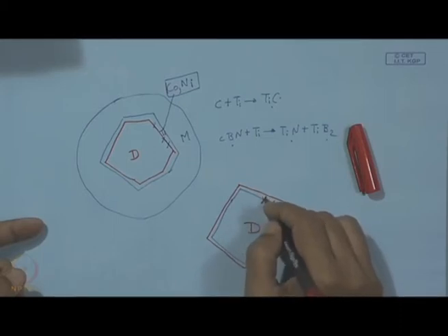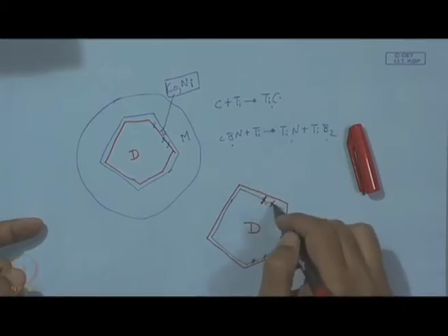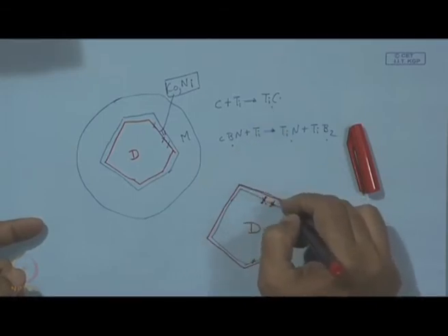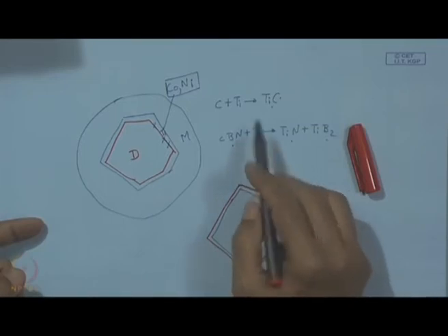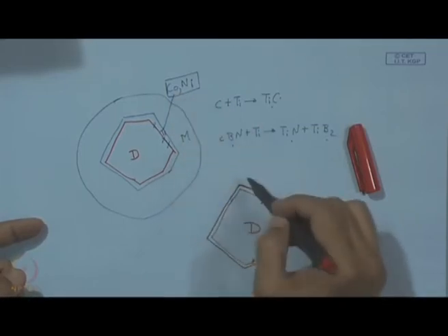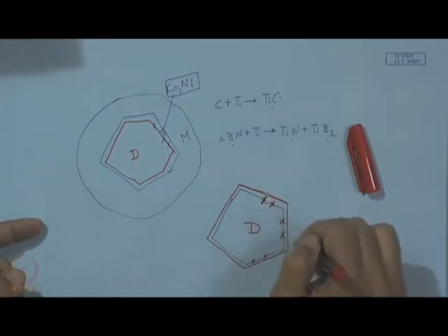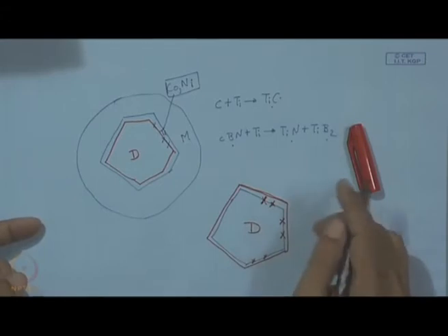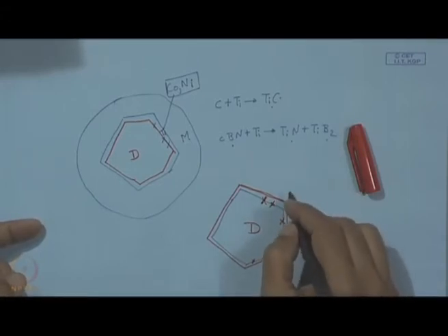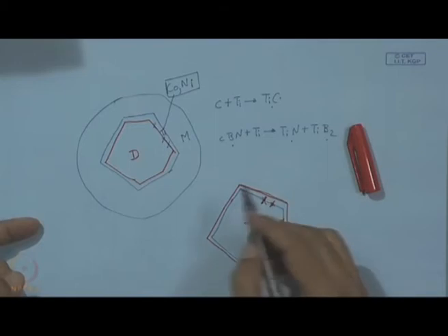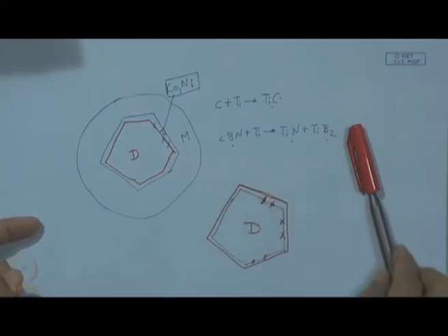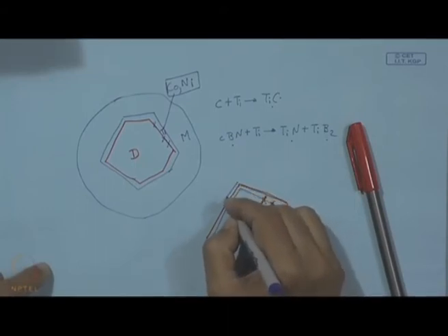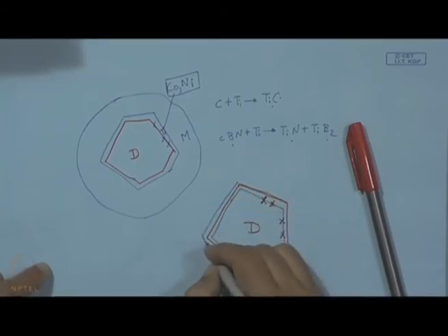However, the whole idea is that here we have titanium carbide formation, but on this side it should be a metallic titanium, and on this metallic titanium conventional metal alloys can have chemical or metallurgical bonding. But if this titanium is exposed to atmosphere, there can be titanium oxide. Now, to prevent that, what is done? It is also a routine practice to put a secondary coating of nickel.